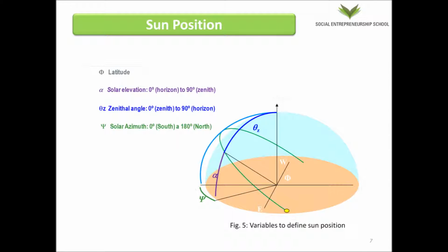There are certain angles relevant in the solar industry. First of all, the latitude is very important. It can tell you a lot, especially the solar resource that you can expect. The higher the latitude value, in positive or negative, meaning the further away from the equator you get, the lower solar resource you can expect.